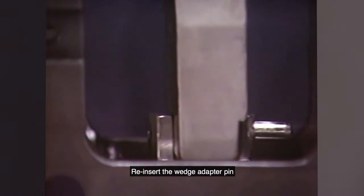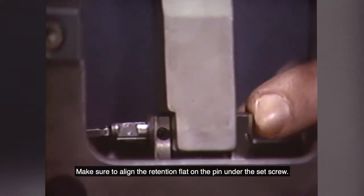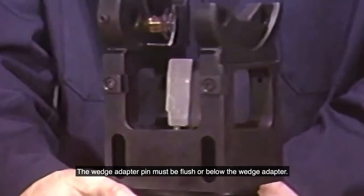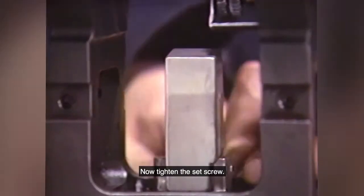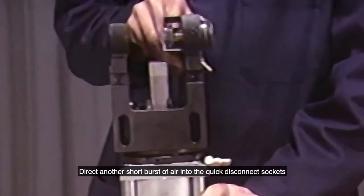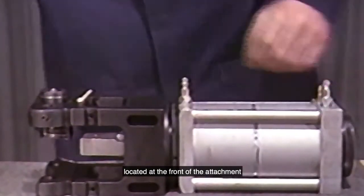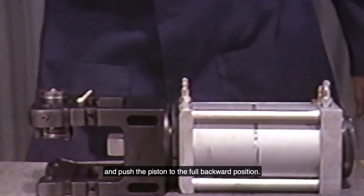Reinsert the wedge adapter pin. Make sure to align the retention flat on the pin under the set screw. The wedge adapter pin must be flush or below the wedge adapter. Now, tighten the set screw. Direct another short burst of air into the quick disconnect sockets located at the front of the attachment and push the piston to the full backward position.